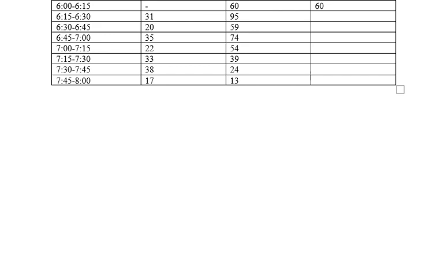For the next time period 95 vehicles departed, okay, and there was no queue earlier, so obviously these 95 vehicles they came in this time interval. So 95, if there had been a queue earlier, I would have subtracted it.